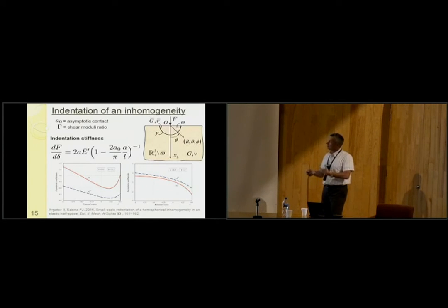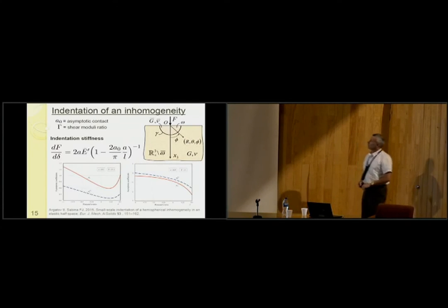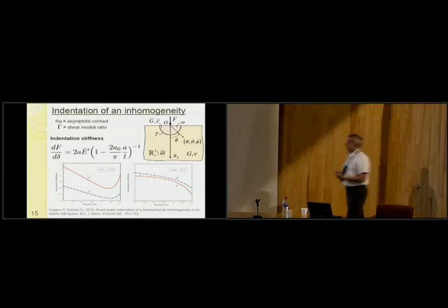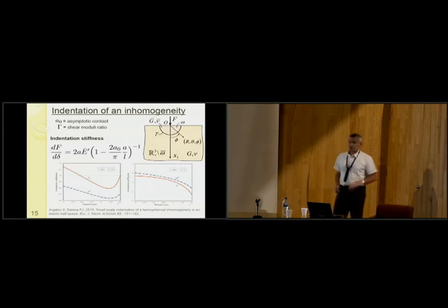And now when we come to this problem and using this projected formula, we can solve inverse problem of identification of material properties, of course, under some usual assumptions that are made in indentation testing, and in particular in the theory of Oliver and Pharr.